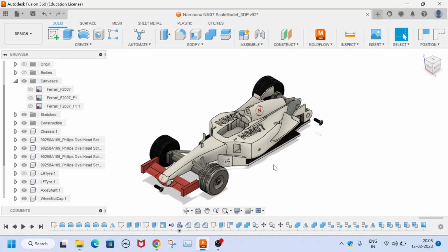And in our college, we are developing a facility called a water tunnel, wherein you can place the 3D printed F1 car model and allow the water to flow around it, and you can inject a color dye into the flowing water, and you can see how the water is flowing. The reason why we chose water instead of air is because water is denser, and hence you can maintain the Reynolds number similarity between the actual F1 car and the model car.